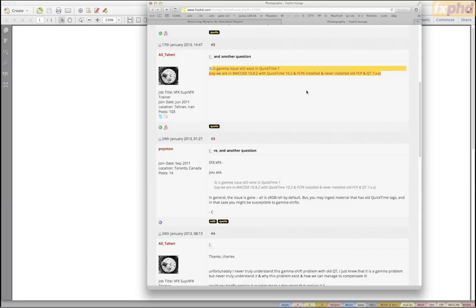So gamma became 2.2. So going forward, the whole Macintosh infrastructure is assuming sRGB numbers whenever the images are in 8 bits or whenever the images are coded in nonlinear forms suitable for direct display.